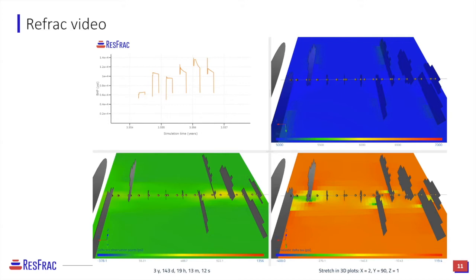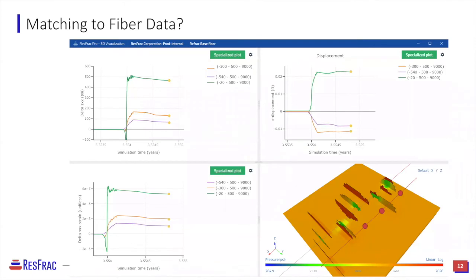What are you using for material properties when you're calculating strain in the far field in ResFrac? Well, it's inputted by the user, but it's a Young's modulus and Poisson's ratio, and then you can also put in layering of those, which is not handled in an exact way, but it's handled in a reasonable, approximate way. In fact, I even have some slides summarizing that, and it's in the technical write-up. The most recent version of the technical write-up talks more about that. And you can do an anisotropy of the Young's modulus between horizontal and vertical. Does that answer the question?